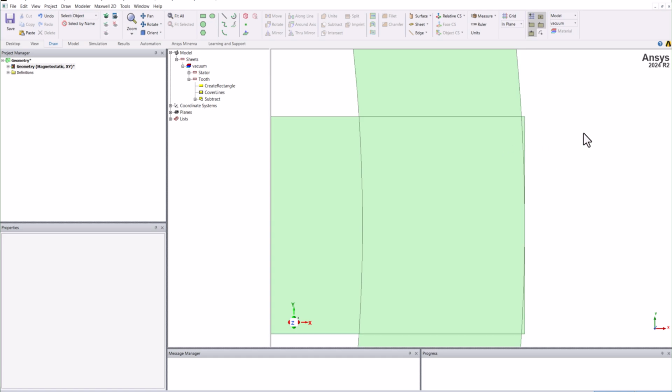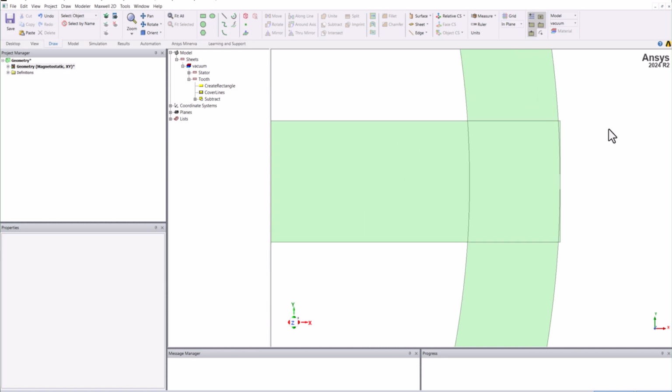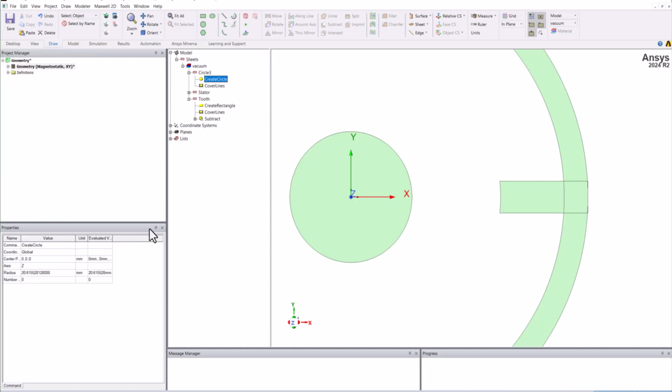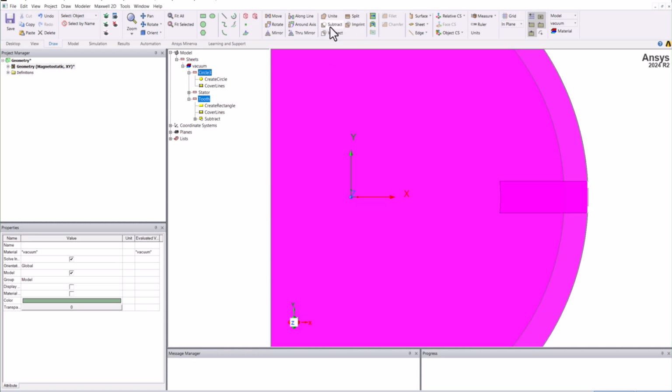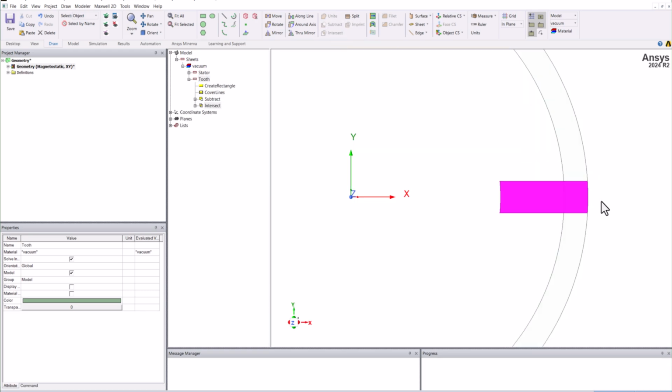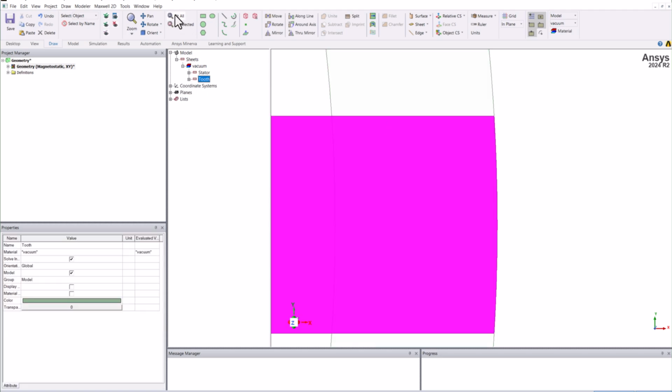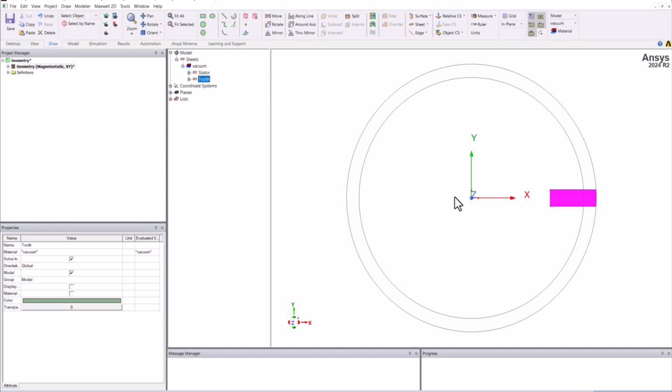So to avoid this, I will create another circle. I will create it as a stator OD by 2, and this time I will just keep an intersection of this. So now you will see that only the curvature based part is there. So now we have our tooth properly formed. This is only one tooth. We have to replicate it throughout the